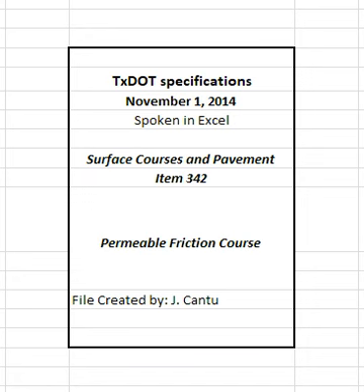4.4.2.1.7 Ignition oven correction factors. Determine the aggregate and asphalt correction factors from the ignition oven in accordance with TEX 236F. Note that the asphalt content correction factor takes into account the % fibers in the mixture so that the fibers are excluded from the binder content determination.